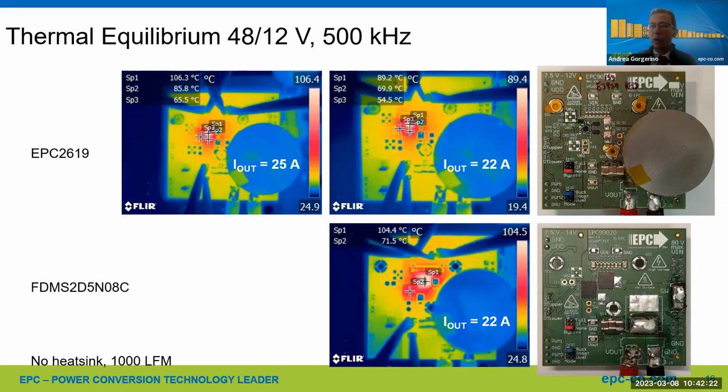So I think that's the first priority. The way to do it, and you can see the example here, I like this slide for that, is basically if you look at the GaN device, you have the power loop going in this vertical direction and the gate loop going 90 degrees off it. So that means you have basically no overlap. That's the first thing you've got to do if you want to switch effectively at high frequencies.